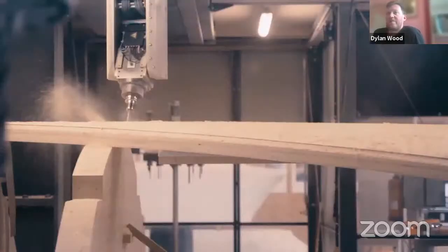Another advantage of this type of approach is that there is no springback from the forming process, and there's very little material waste, which means that the only type of finish work that's needed is really a careful trimming of the edge, and almost like a dentist, the robot coming in very precisely with a 3 millimeter drill bit to add the connection detailing and the pilot holes for the crossing screws. So if you imagine that the part is basically already shaped, all the robot really needs to do is to come in and precisely add a couple of holes and finish and clean the edges around the connections precisely.